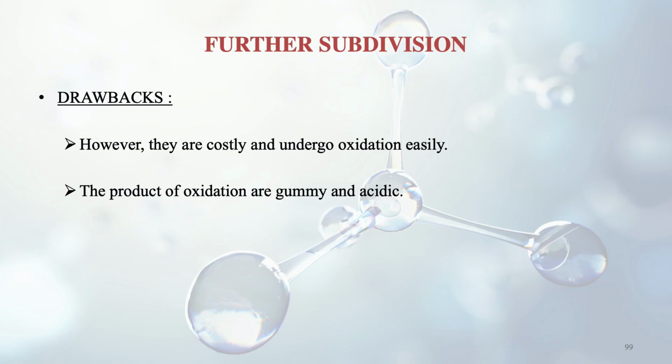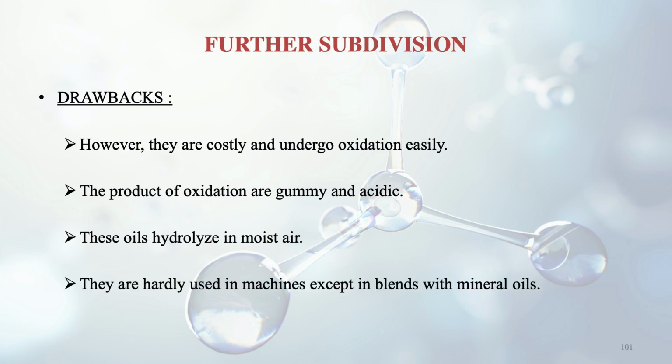So it will be sticking. Instead of providing lubrication, they will be increasing the friction. And these oils hydrolyze in moist air. So that is a drawback, because then they will have water inside also. And they are hardly used in machines except in blended oils.